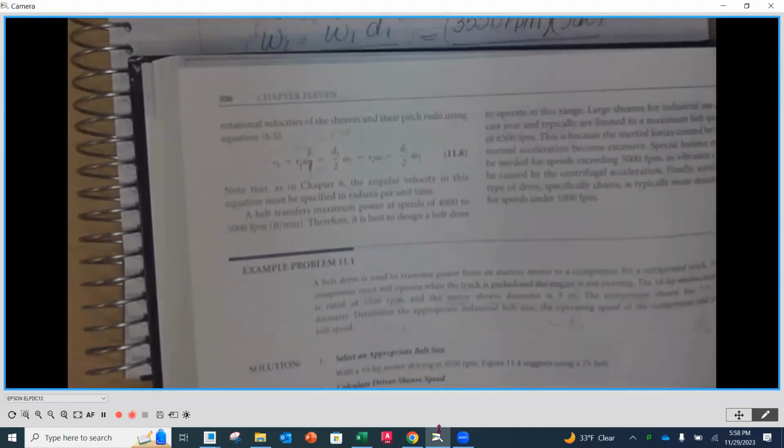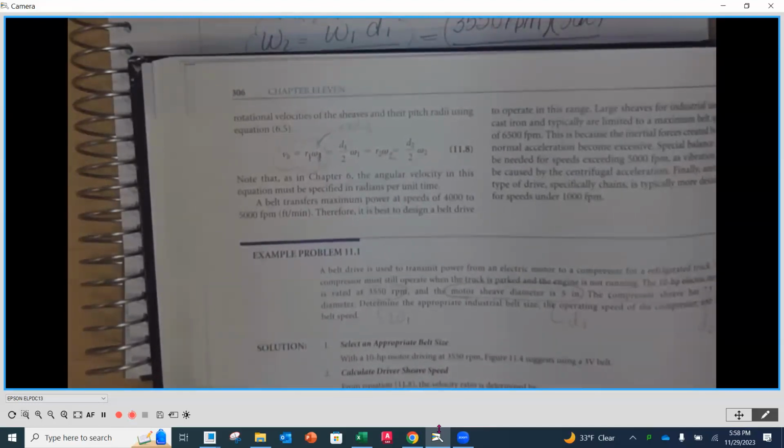So when we're in design problems, we will actually be calculating a design horsepower based on some more information and some additional charts. So we're going to use just the horsepower here. And maybe you're thinking it's no big deal, but design horsepower is more than just regular horsepower. They're just not taking that into consideration here. So I want you to know that when we see design, there's usually something to it. It's not strictly the textbook off-the-motor horsepower, but that's what we're using here.